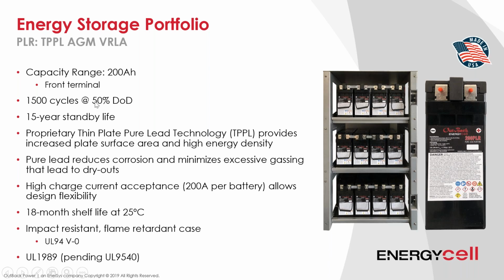So I would also put the low battery cutout down to about 80% of capacity in this application. That's going to give you more capacity as well. It's going to drop your cycle life to 675, but again, it's still going to give you more cycles than the battery's going to last anyway. So this would be for emergency backup applications.